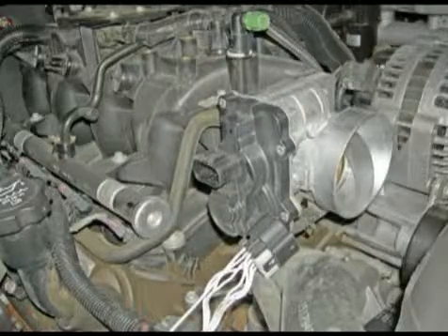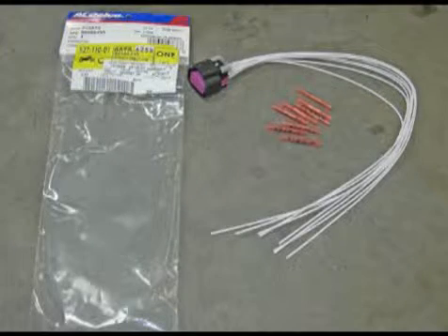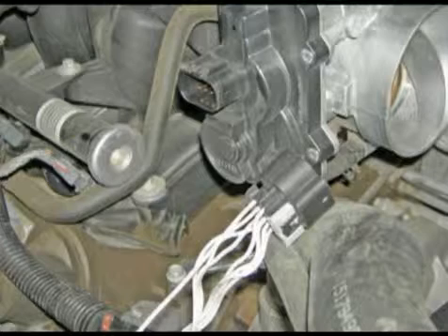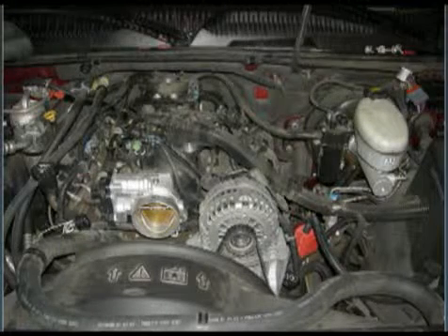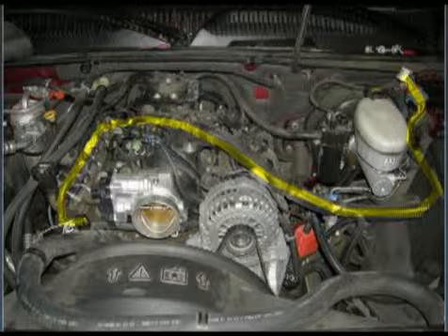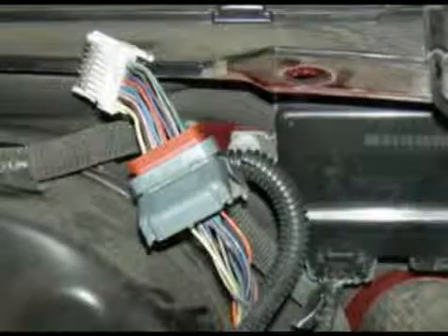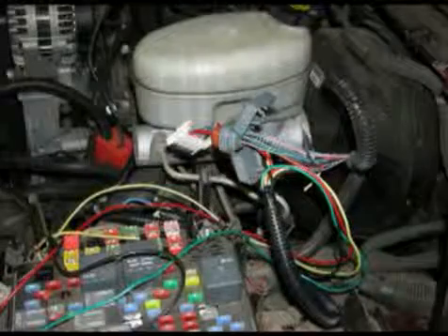If you find broken wires near the throttle body connector, you may be tempted to order a repair harness connector and just replace the connector. After the connector replacement, the problem will still be present. Save yourself time and aggravation by replacing the complete harness from the throttle body to the TAC module by manufacturing one. The throttle body connector is available, but the TAC module connector is not, so you'll have to reuse the original one from the vehicle.